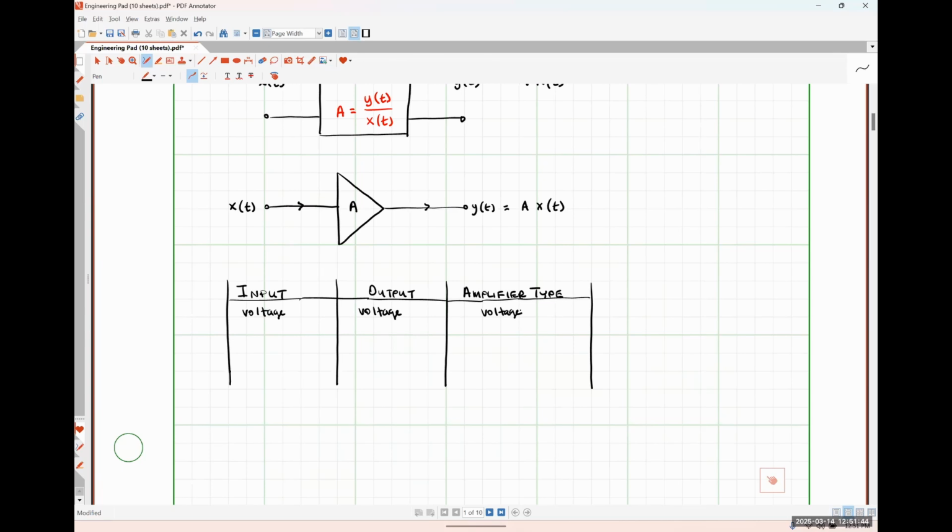As a quick tangent, the reason why AM radio stations have to broadcast at such high signal powers is because the wavelength of those radio signals is so long that the antenna lengths on our cars and stuff like that are very inefficient at picking up those signals. So they have to broadcast at a really high power so that we can actually pick up enough of that signal to do anything with. FM radio stations, satellite radio stations, things like that get to broadcast at much lower signal powers because the length of our antennas is comparable to the wavelength of those signals. And so we don't lose as much of the signal power when we pick those up.